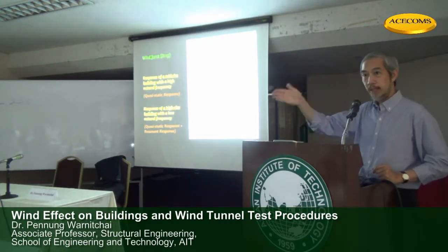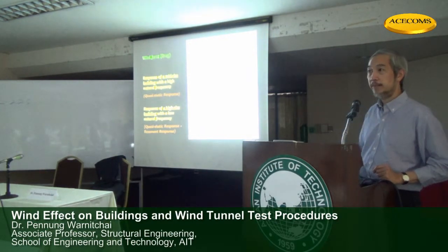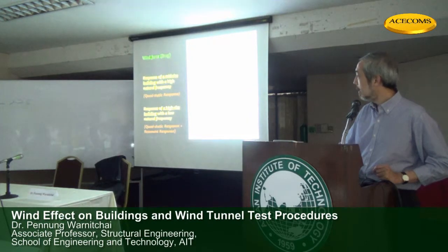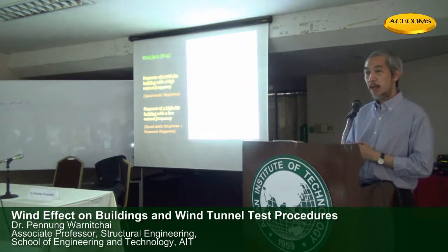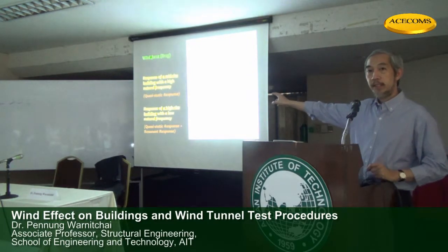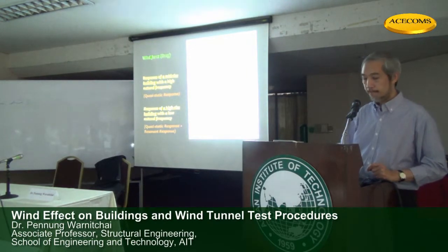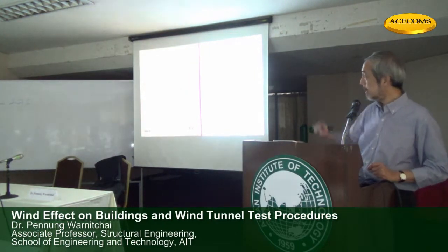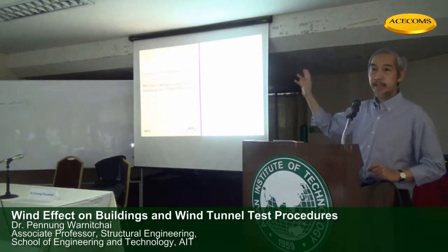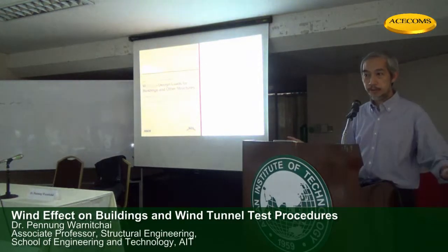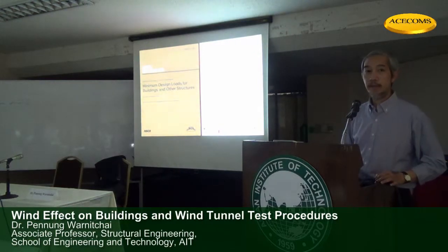The structure will sway back and forth, oscillating around this quasi-static response. So you have an additional resonance component. The methodology to handle this is called gust response factor analysis. If you look at the American standard, Australian standard, Canadian standard, Japanese standard, they all use the gust response factor procedure to handle this for the design of tall buildings.